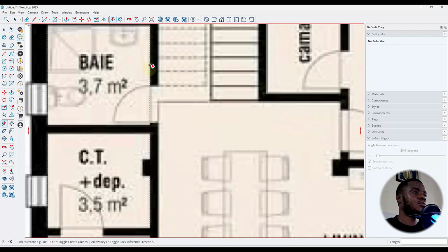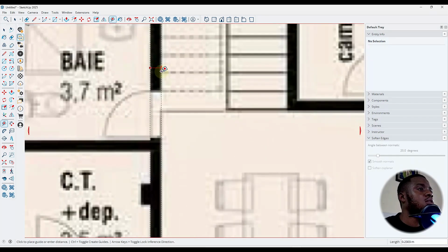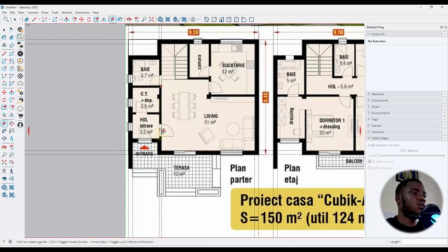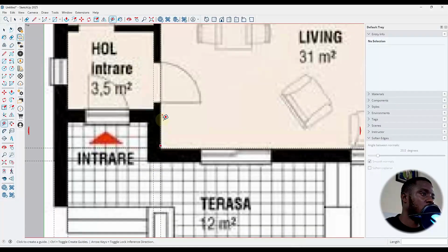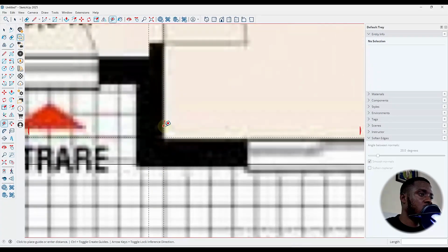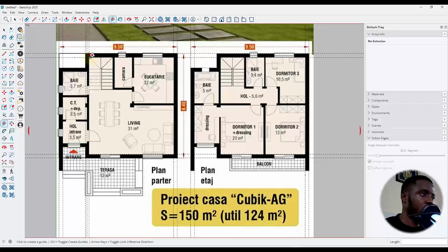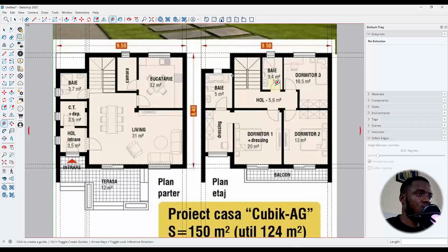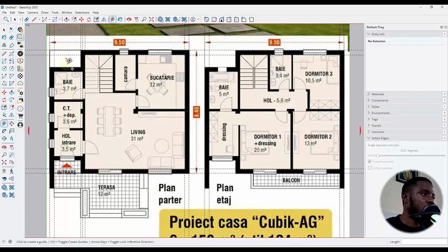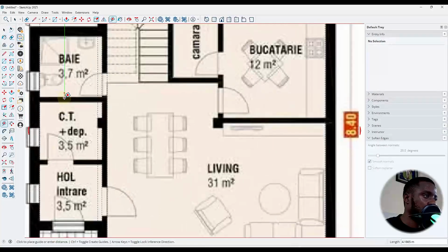All right, so let's see our block size here. Block size here is about, we're going to use about 225. So 0.225 for this block size to cater for that area. And this place we need to use a block thickness of 400, which makes sense. Okay, and we can actually transfer that to what we did here, but before that we'll just quickly block out everything and start to show you how it works.